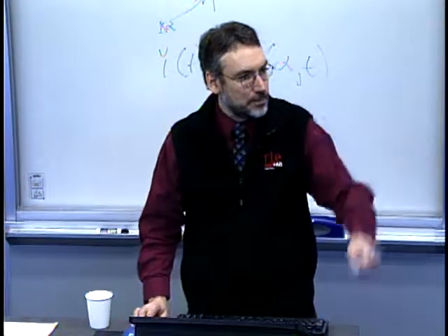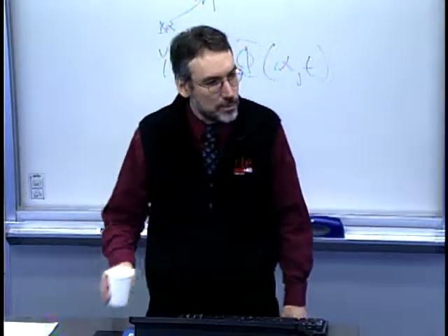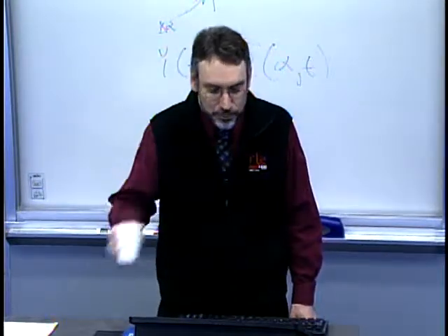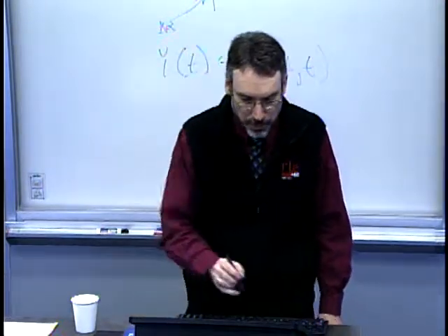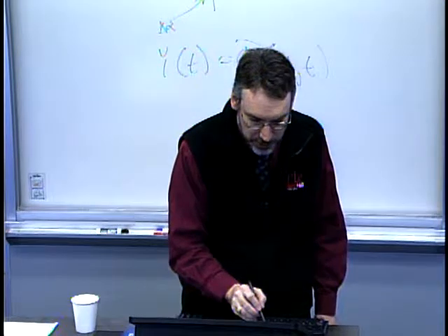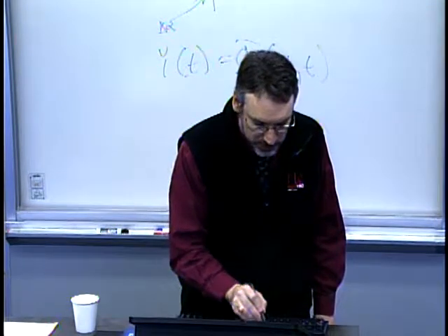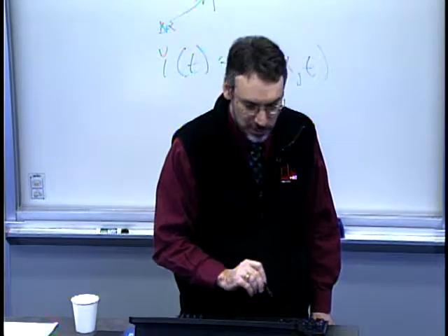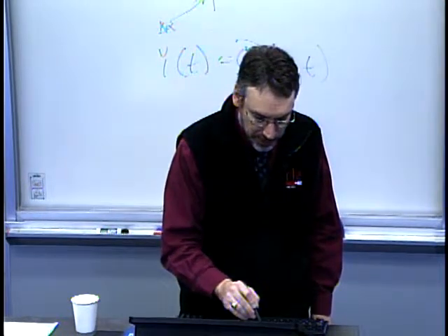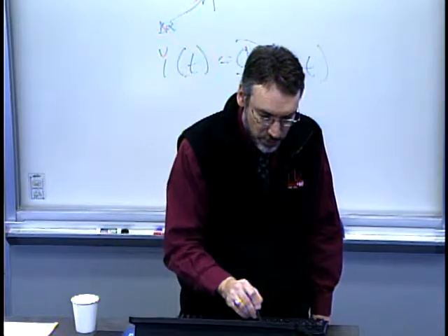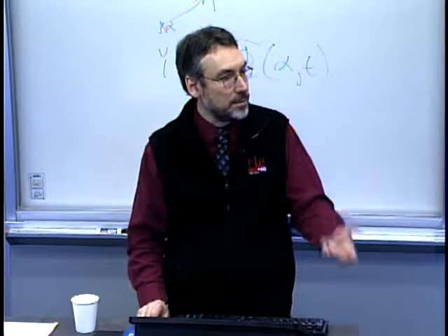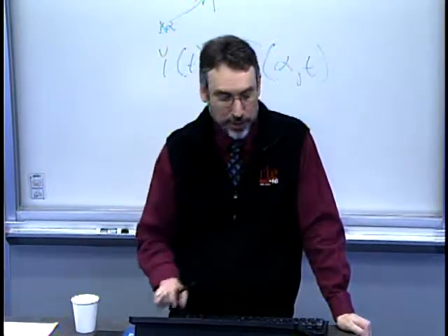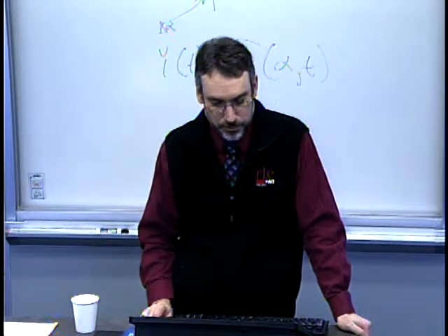The variation, I guess the spread on the first shift is much higher across the piece than the spread on the second shift. Okay, so one observation is, if we were just looking, well, right here, this is a good one, where inner, middle, and outer are all close together. But your point is, generally, we're seeing a very huge spread in the measurements within that particular part, right? Yeah, than we do over here. It looks different between first shift and second shift. It seems as if there's much better control on second shift. It's a much tighter band.